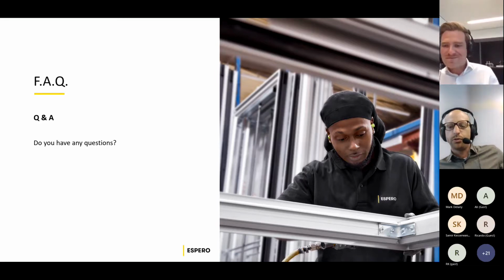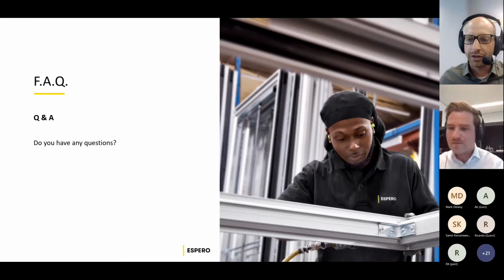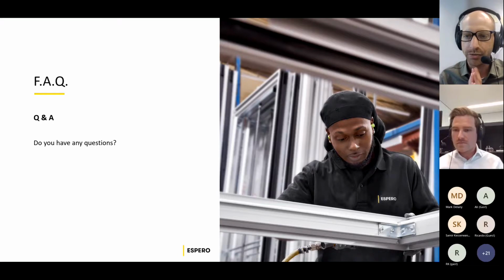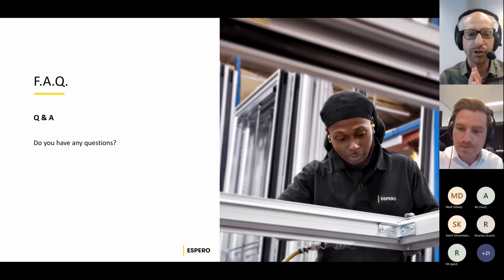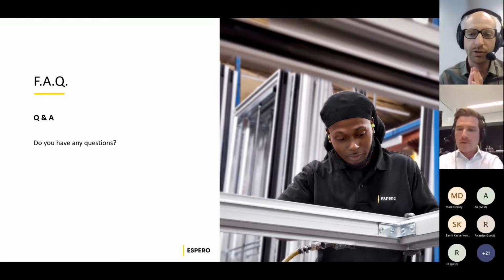Yep, I can answer the question of Mark Atkins about the finish and the frames. It is exactly as you state in your question, that you hang the frames into the track and then you put the boards into it, and the absorption material is already assembled into the frame. The bitumen, the mass, is already applied to the finish if the sound insulation value needs bitumen, of course.